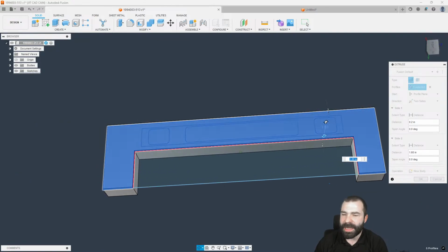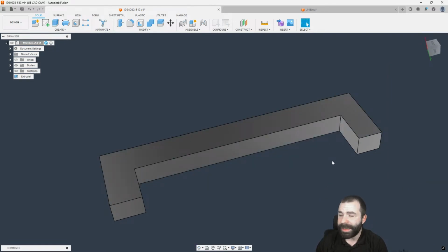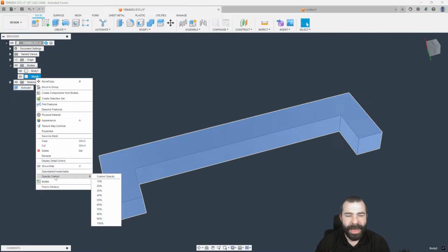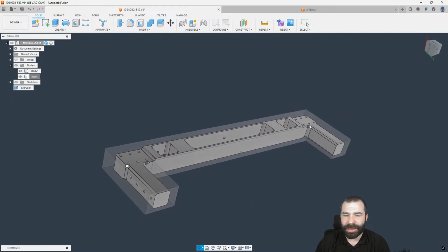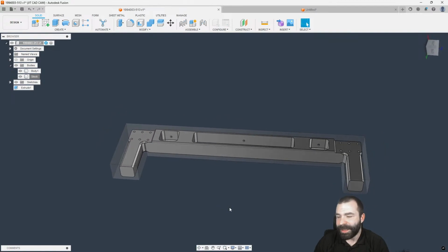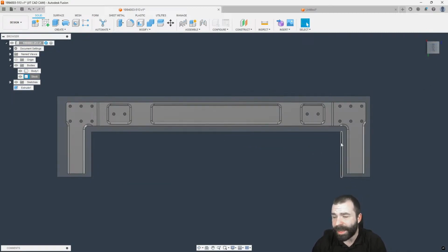Now, you can see with a new body, I have my old part kind of floating around in the background. And a trick that I personally use all the time is go to that body or component and relabel that as stock so that we know. But I like to change the opacity so that you can see the ghost image of the stock versus the part. As somebody is mentioning out there, your desired method for water jet stock is to project the body and offset the sketch. Yep, 100%. So you can do that. I'm just doing it a little bit simpler, but because you would have had a projected sketch, you could extrude that, Max.